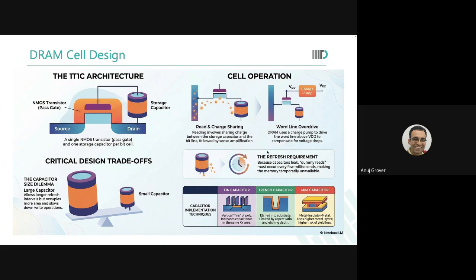So one thing that we established was whether it is SRAMs or DRAMs, they are all charge storage based levels. They store charge, and when they store charge, that is where they say whether I am storing a 1 or a 0. And in SRAMs, whatever charge is there, by virtue of there being a latch there, that charge is replenished.